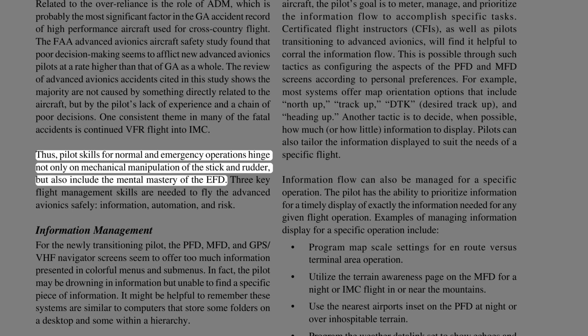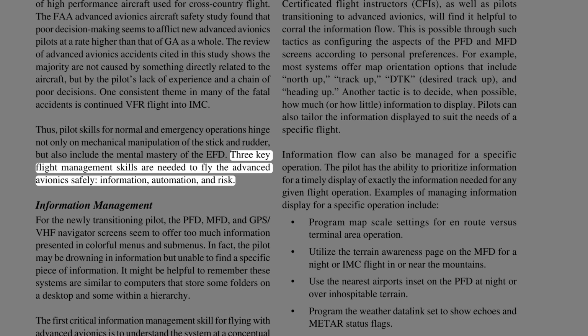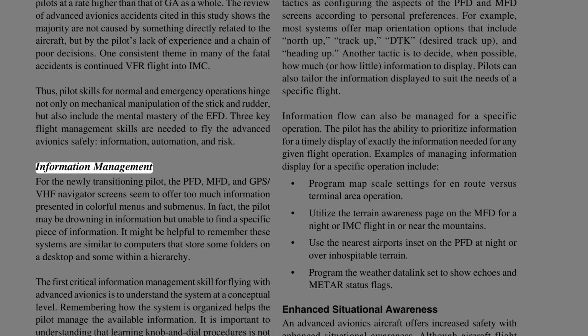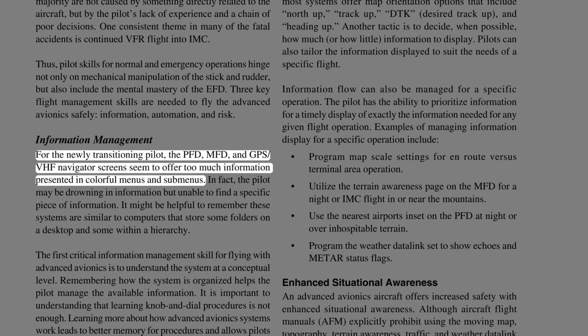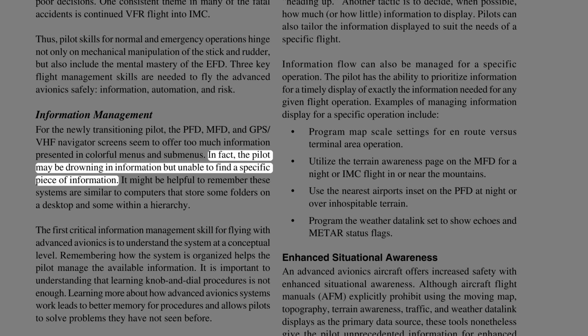Thus, pilot skills for normal and emergency operations hinge not only on mechanical manipulation of the stick and rudder, but also include the mental mastery of the EFD. Three key flight management skills are needed to fly the advanced avionics safely: information, automation, and risk. Information management. For the newly transitioning pilot, the PFD, MFD, and GPS, VHF navigator screens seem to offer too much information presented in colorful menus and submenus. In fact, the pilot may be drowning in information but unable to find a specific piece of information.